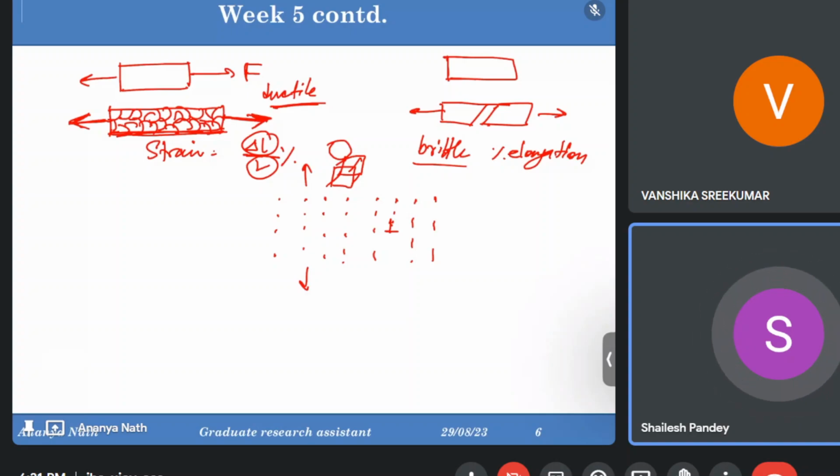And the second digit indicates how much strain hardening remains after the stabilization. So this remains the second digit. And what about this third digit, 1? Like if we take the example 5083H321. Where did you see this type of three-digit nomenclature?